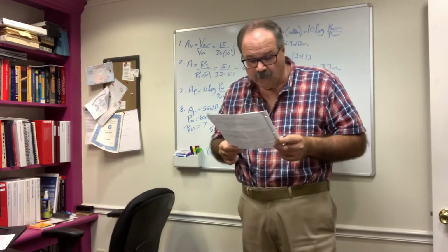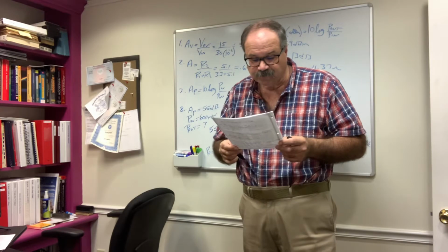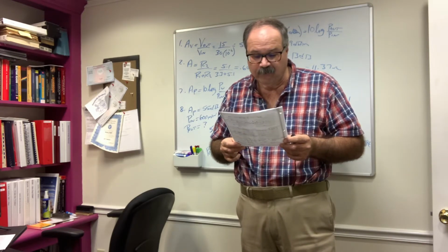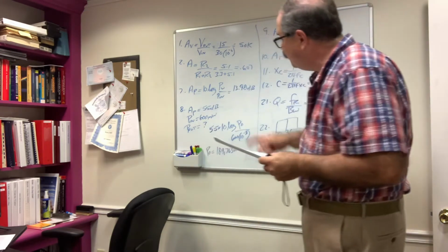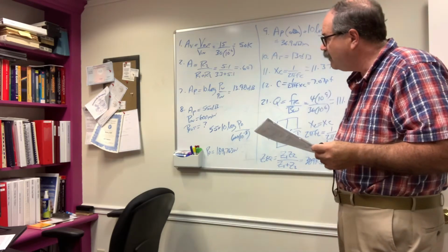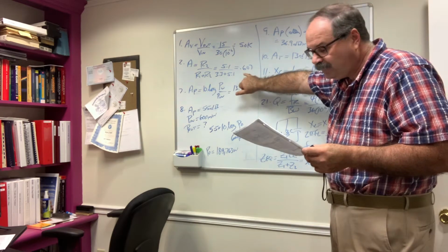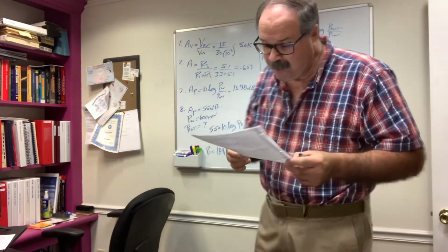50K. Question 2, what is the attenuation of a voltage divider circuit like shown in figure 2-3 of our text, where R1 is 3.3 k ohms and R2 is 5.1 k ohms? Using the voltage divider expression, R2 divided by R1 plus R2, plug in the numbers and we will get an overall attenuation of 0.607.